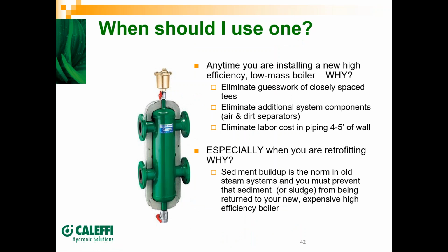When should you use one of these? Anytime you're installing a low mass or a high efficiency type boiler, especially one that's going to be susceptible to air and dirt in the system.